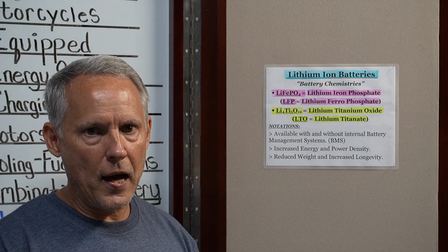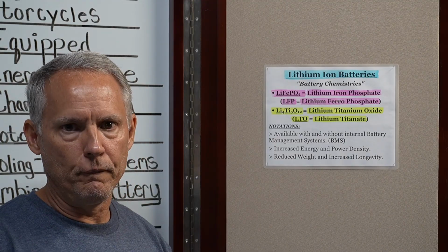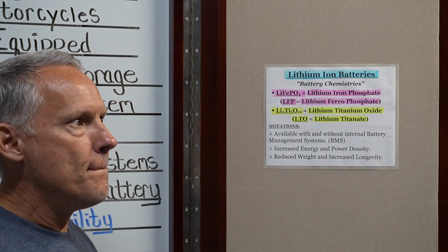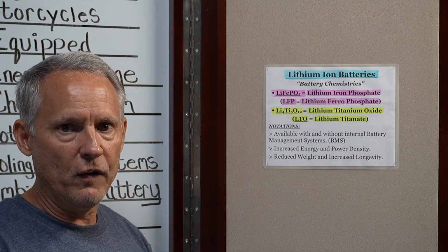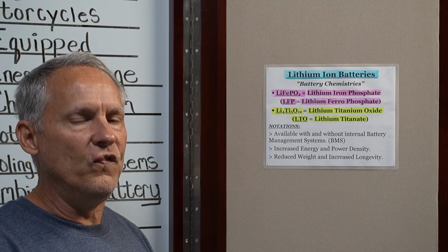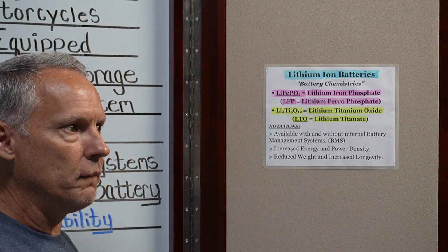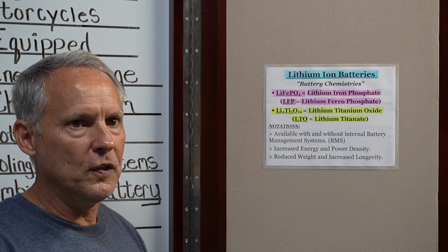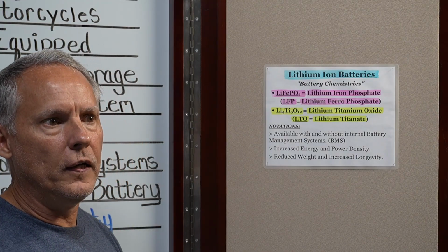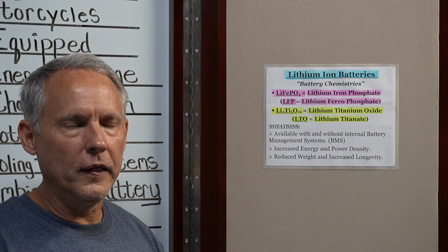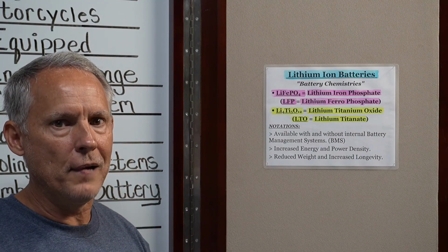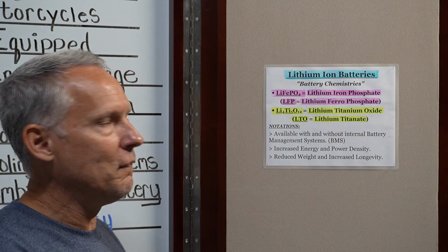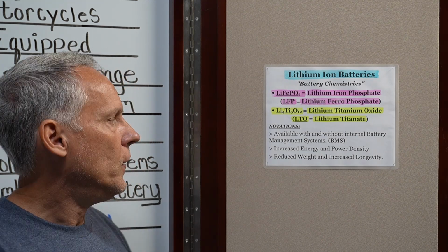If you're getting into the lithium battery world and you want to go down that road, which is fine, I have no problem with that whatsoever, you better feel very confident that the manufacturer of that battery is very reputable. If you put one in a motorcycle and you're sitting on that battery stopped in traffic, I ride motorcycles, and you know how hot it gets. It gets extremely hot. Well, you're sitting on that battery. It's hotter than where the battery is stored. And these batteries can be very temperamental when it comes to temperature, right?